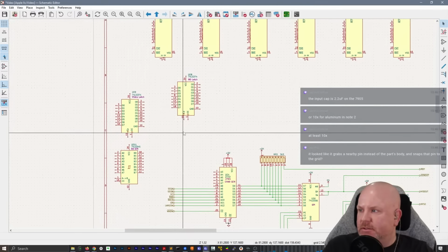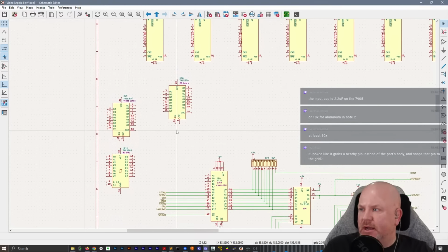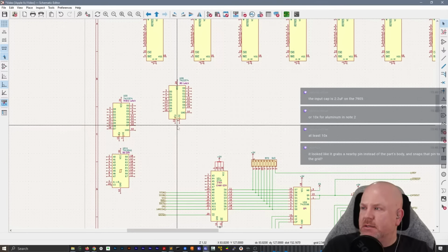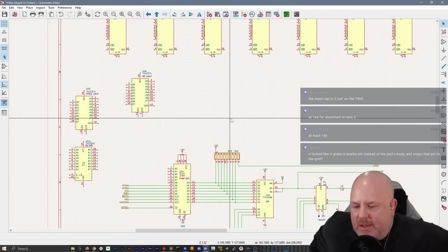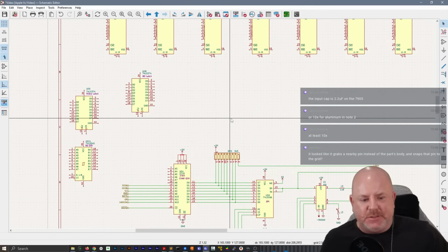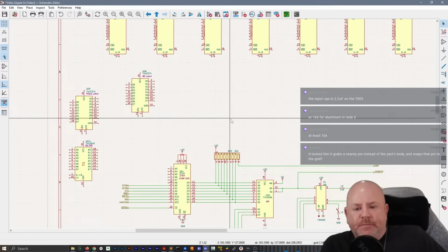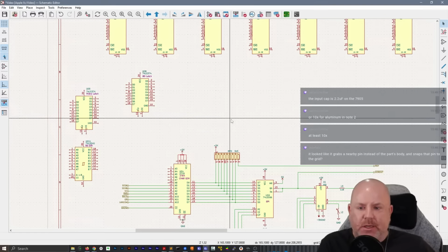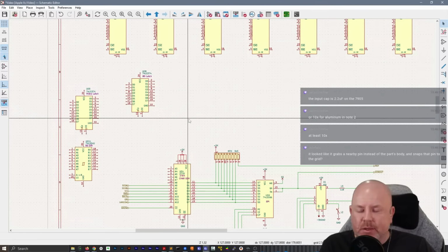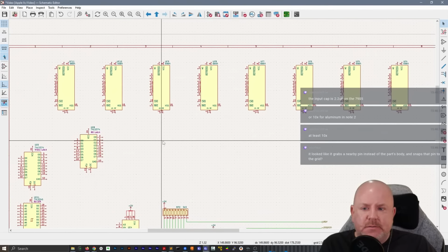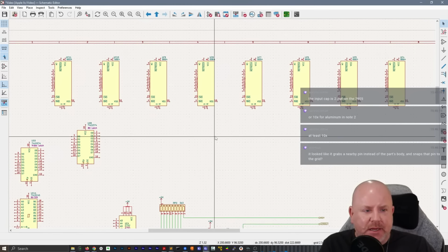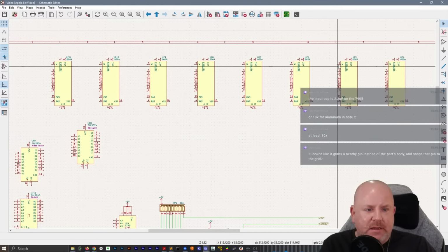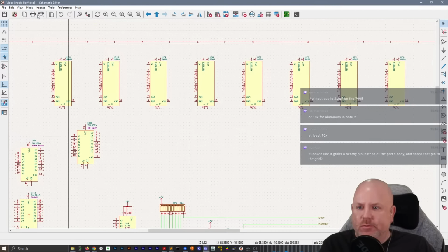Yeah, I'm not sure. So Aaron, where are you getting that? Are you talking about the data sheet for the 7905? I appreciate you looking at that, but I don't know that they would have followed the data sheet. In fact, it looks like they didn't, because I don't think they have a decoupling cap on the input. But yeah, what you described might be what's going on. I'm just not totally following what it's doing.